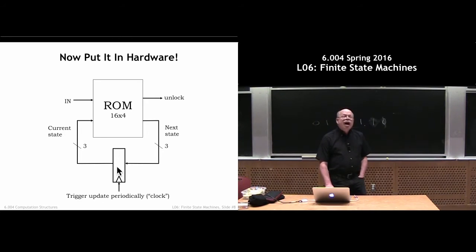And this register is not going to get confused at all. It's designed to be able to latch inputs in such a way. We do have to guarantee that we meet the hold time here. In other words, this value will start to change when we do the new latch, but this value has to stay stable for a certain length of time after the rising clock edge for this latch to work correctly.